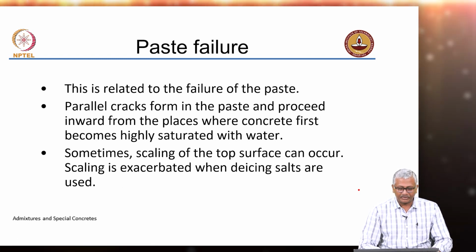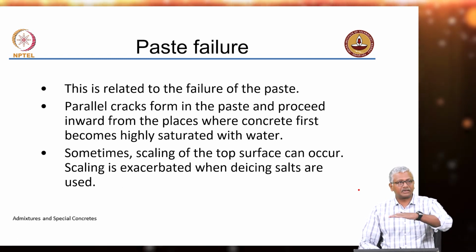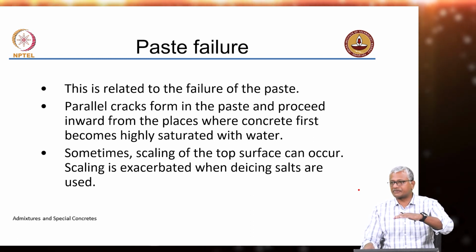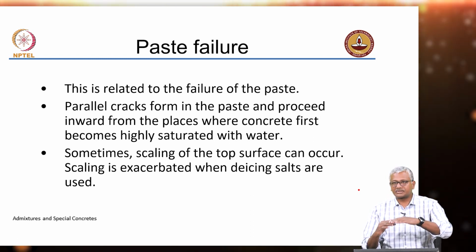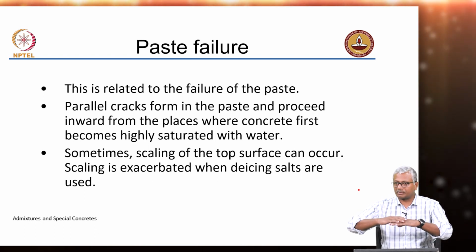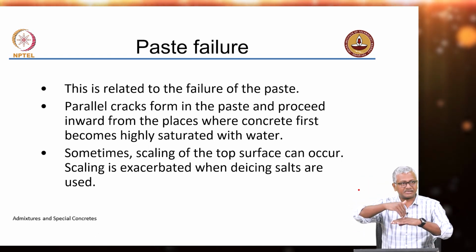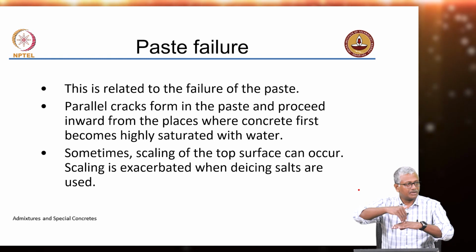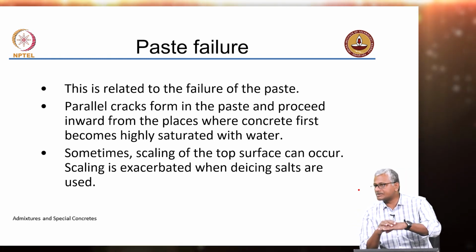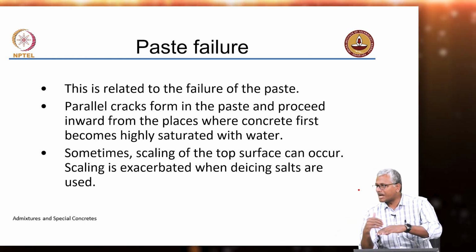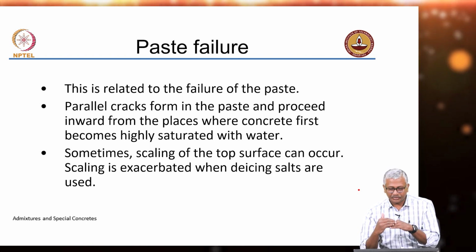Okay. So, if you imagine a surface of the concrete which is the highest portion of your concrete, the freezing basically will start from the surface, okay, and wherever water availability is obviously there from the external environment, that is going to add to your freezing damage, okay.